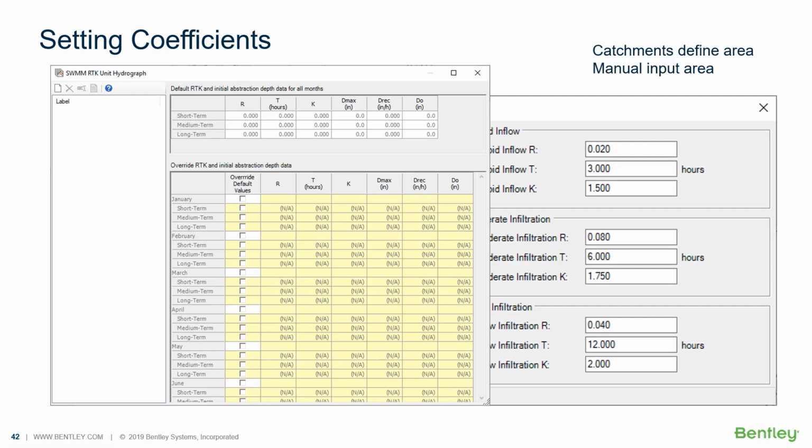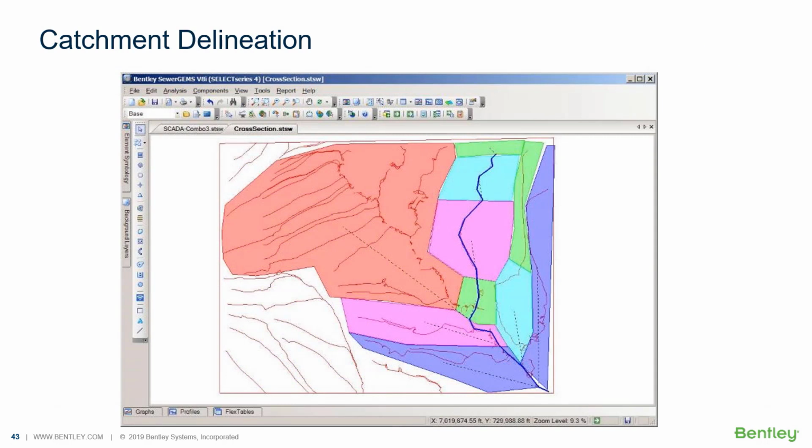And then the next thing is, what do the catchments look like? Because remember now, you're applying this to a catchment. We're talking about inches of rainfall, but it depends on how big the catchment is. And nowadays, we've come a long way in catchment delineation, where in the old days, you'd have to sit there with a topo map and try to draw the boundaries of each catchment.